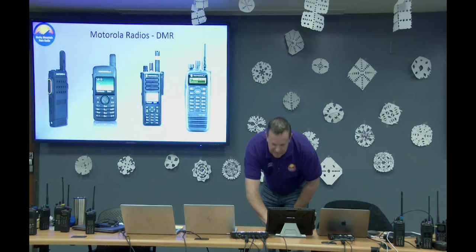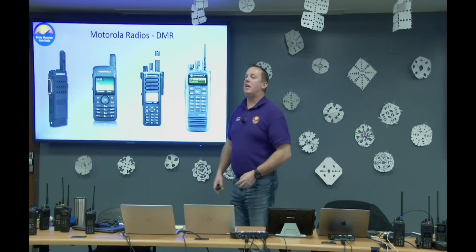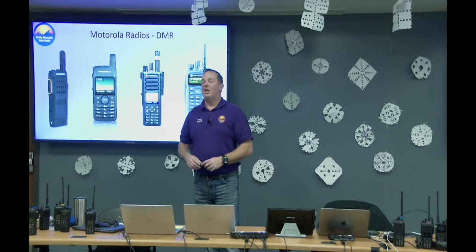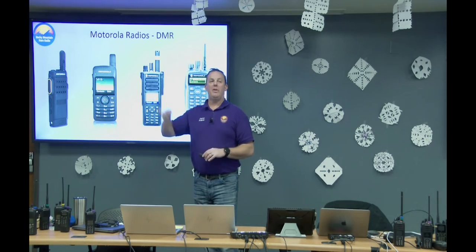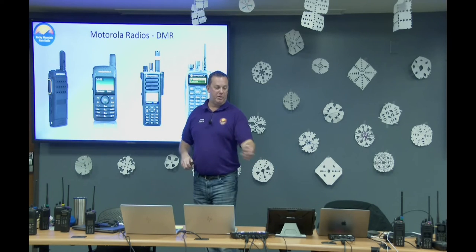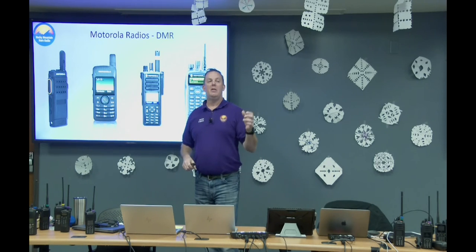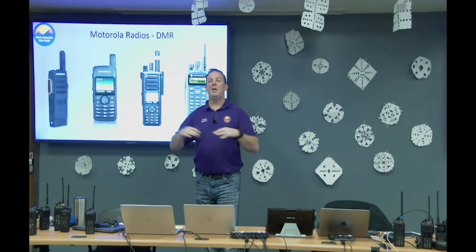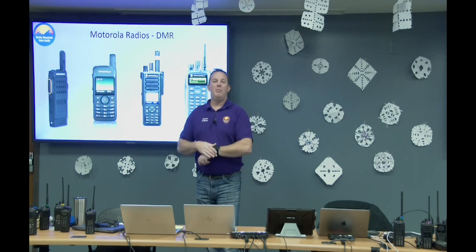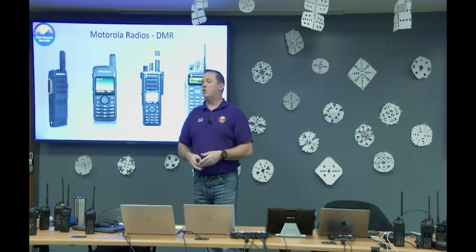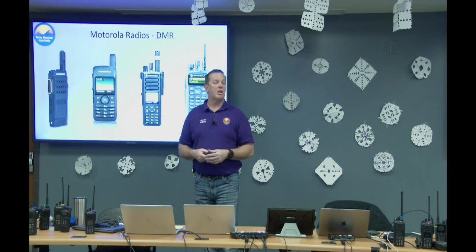The band split when you're buying used radios, that's really important. Some radios have multiple ranges of frequencies they can work in. So for example, in the chat, the UHF there can be low split, high split. Some of them have 3 splits. If you're looking at a radio, make sure it actually covers the band that you're interested in. Make sure it covers the ham band.